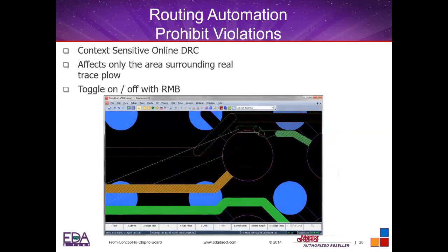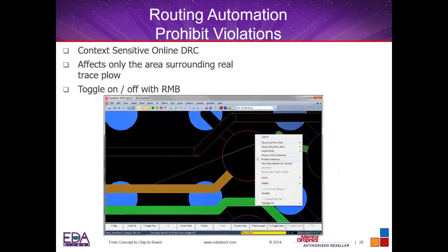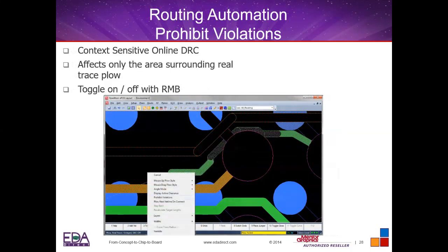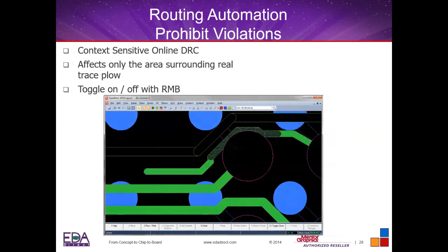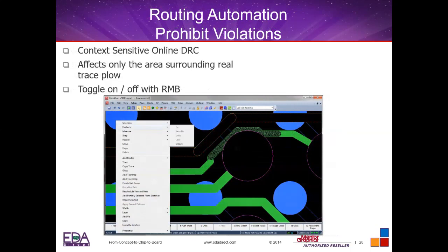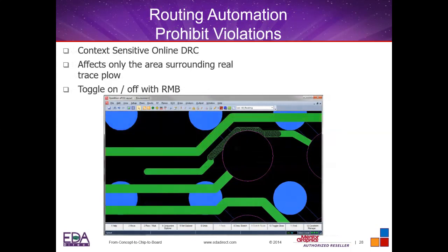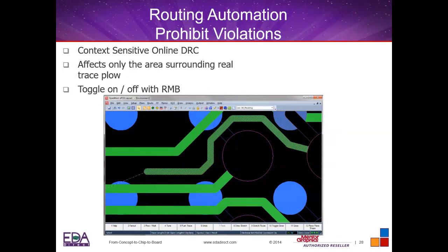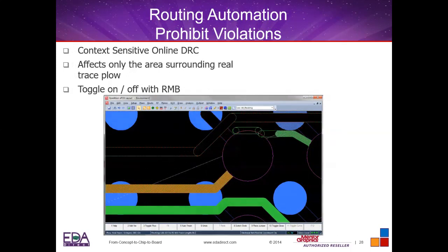You've also got the capability to place lines in with the DRC turned on, but sometimes you're routing the line and you know that it's going to fit in there, but you've got locked traces, for example, and you don't want to unlock that yet. You just want to get a section in there and come back to it later. What's nice with the PADS Professional tool is we can lay those traces in there, unlock the ones that we want, and then come back in and repair those traces that had DRC errors. It'll look through the whole design and just clean those up for you.